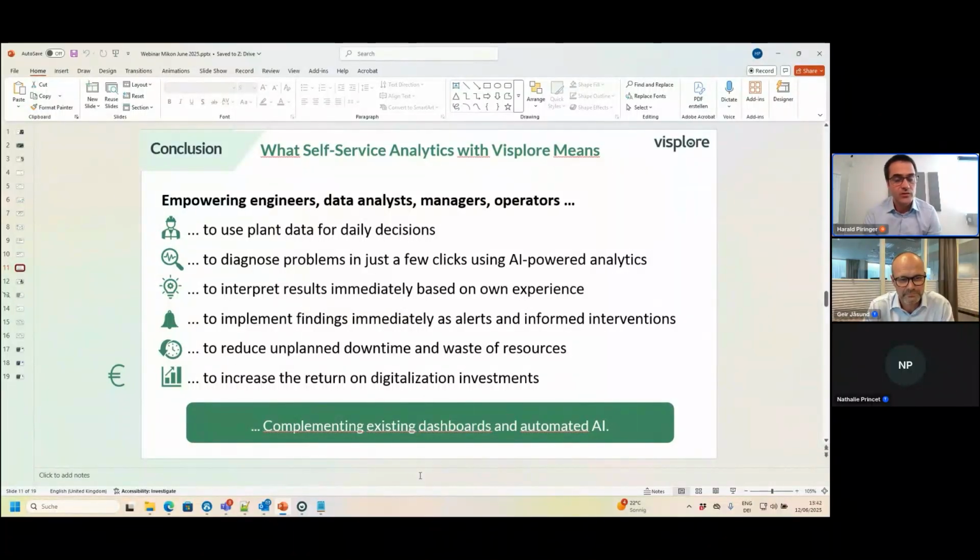there, what our users typically do is they appreciate Visplore a lot for using features such as pattern search to extract specific phases of a batch, or sometimes the entire batches, overlay them on top of each other, and make it very easy to correlate with outcomes of the batches, such as yield or some kind of purity KPIs, in order to find out what the golden batch profile looks like. Then they use this profile to optimize the process, and also to monitor how this relates. This would be a very typical use case in batch production.